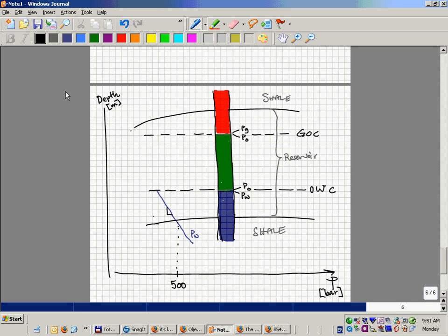And how much pressure will that be? Yeah, it's 1 extra bar of pressure. It's 1,000 times 10, that's 10,000, times 10 is 100,000 Pascal. And 100,000 Pascal is 1 bar. So you go from 1 bar to 2 bar at the bottom of the swimming pool. So this is basically given by the water density times G. That's the slope.